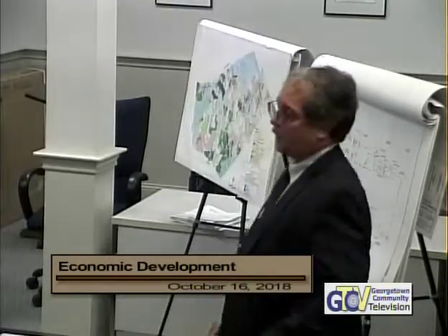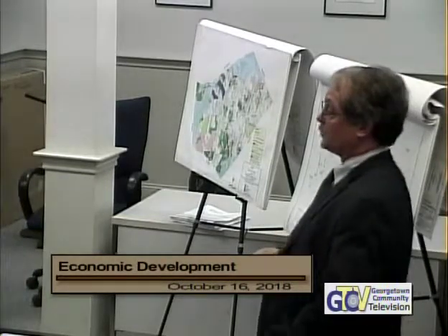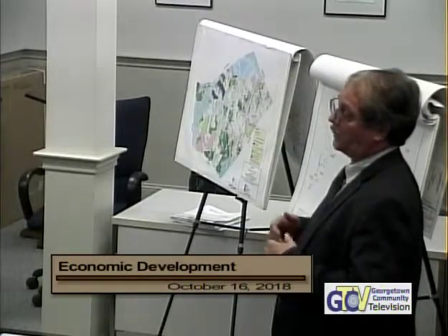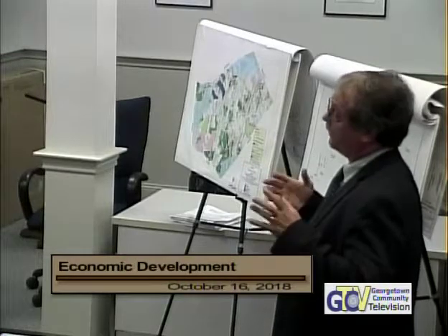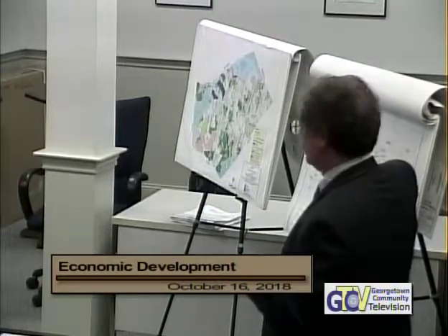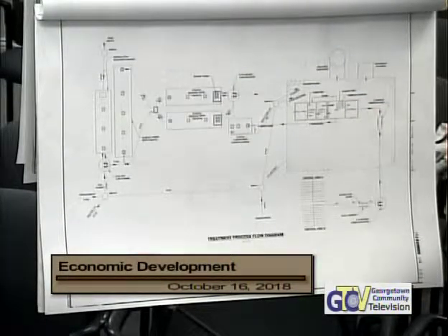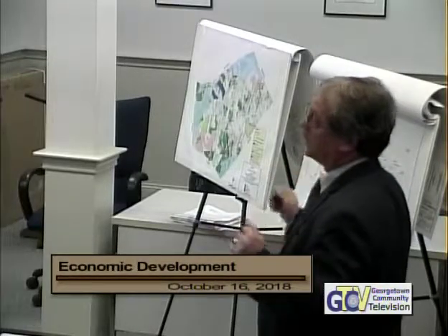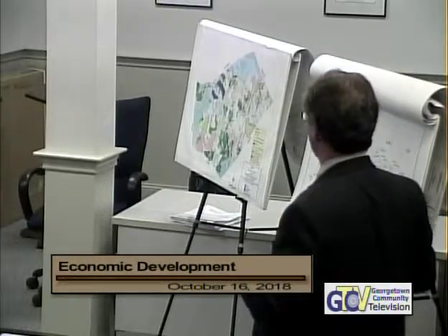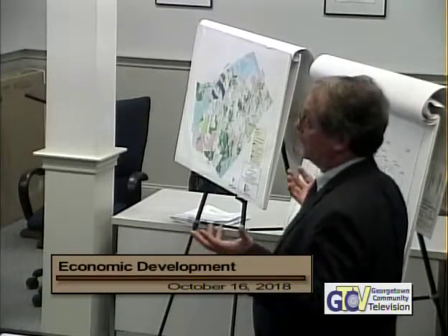This is typically a packaged treatment plant that we're talking about. So in some cases, there are some of these components that can just be tanks underground. In other cases, they require an operations building. In some cases, they need to have the entire process in the operations building. Okay. In this case, this one was using basically a membrane activated sludge system. And in terms of the best quality for effluent, a membrane system is the best quality. Everything that gets treated in the system has to pass through a 1 to 2 micron filter. And basically the water comes out looking very clean, like drinking water. And in terms of treatment performance, the BOD, the TSS, all these are typically less than 3 or non-detect.